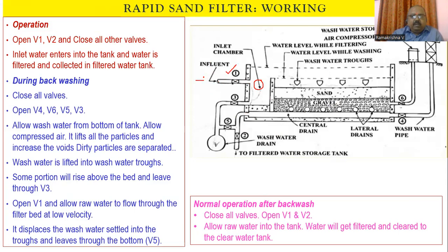The raw water will be coming through this wall. By opening this wall, water will enter the inlet chamber. Now you can see here, this is the weir, and water will be overflowing this weir into the bed. So this is the top layer of the water level. Normally we represent it with a small triangle here. So that is the water level there.